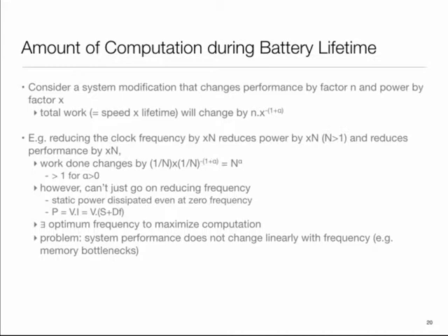In an ideal battery, if I slow the processor down by a certain frequency, and if its power changed by a factor of n, the battery should last the same amount of time, but not if there are non-idealities present. What this means is that as I reduce the frequency, because I'm lowering the current, I'm moving left on that plot, so I can get more energy out of the battery.